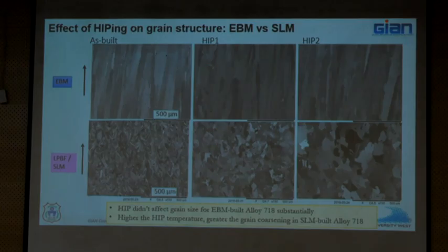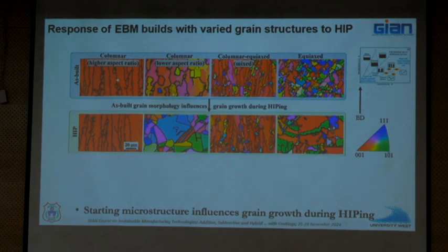And we find that there is more grain coarsening in case of SLM for some reason. You also see a structure that is very different. In one case, you have a columnar structure. In another case, at least when you start, you have an equiaxed structure. Correct. So it's good for you to know that these things can happen, right?